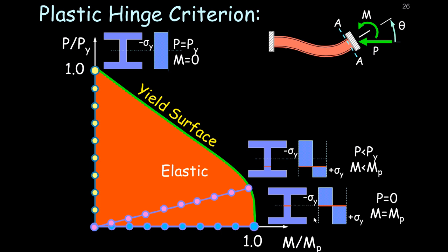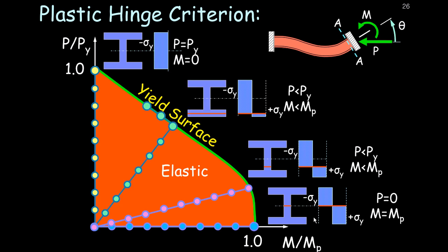If your axial force and bending moment for the member are within this yield surface, the member is elastic. If it hits the yield surface, we need to zero that stiffness and call it yielded or plastic. Now one of the things about this yield surface is a program like MASTAN won't let you get outside of the yield surface. It will actually constrain the movement. So if you get some yielding, the program can take on additional axial force, but it would have to redistribute bending moment to do that.